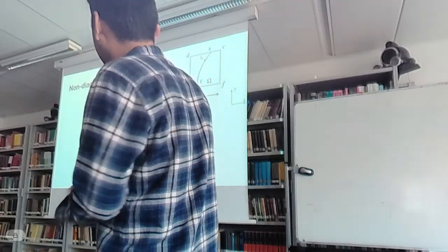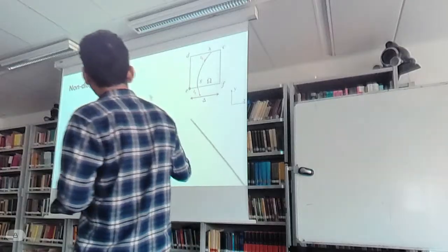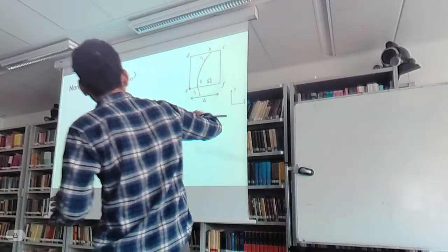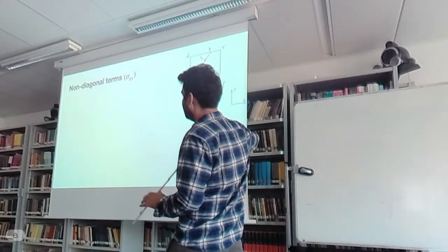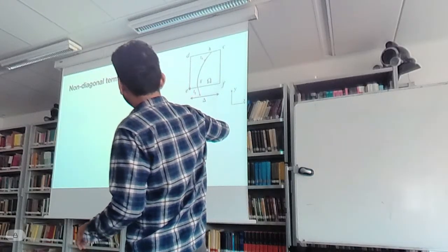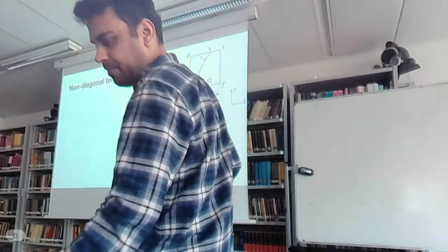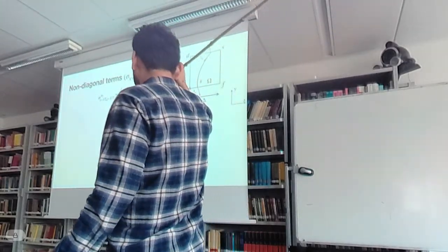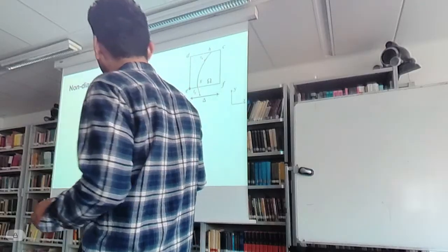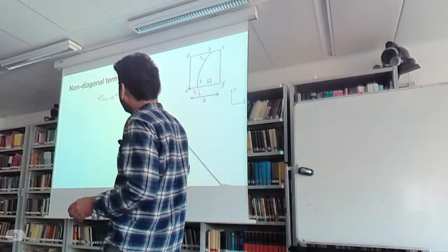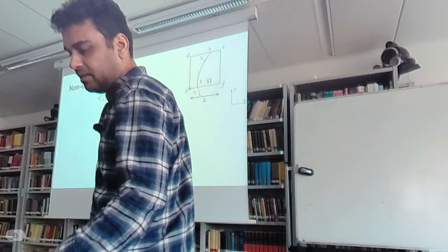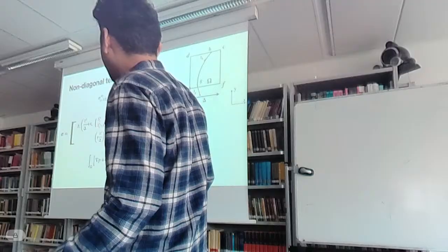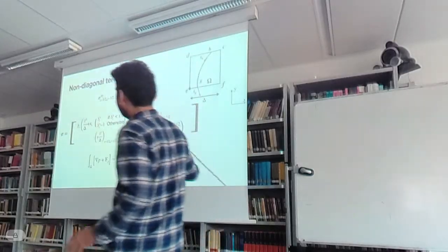So you derive the diagonal element, and for the non-diagonal terms, we look at a control volume like this, where you have an interface that now cuts the horizontal faces, and in this case it's relatively simpler because we are defining this at the vertex center, so there is no jump of pressure, and then you have the non-diagonal term, which is simply gamma t by delta, and this is how the full tensor would look.